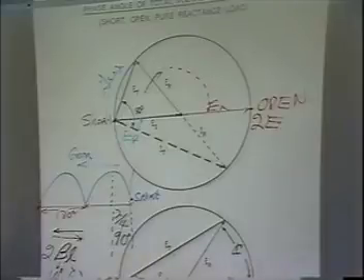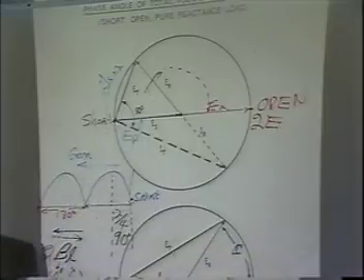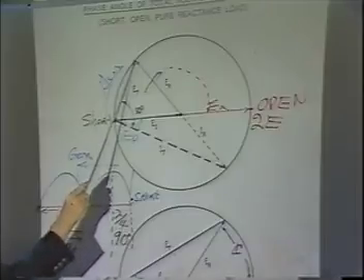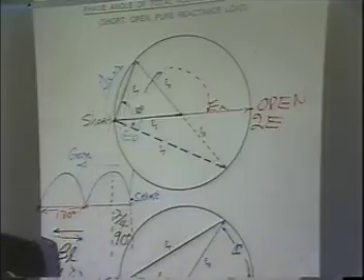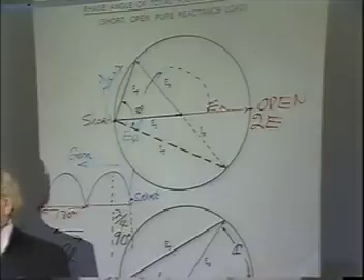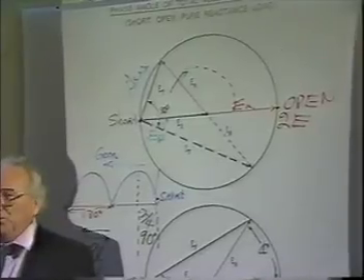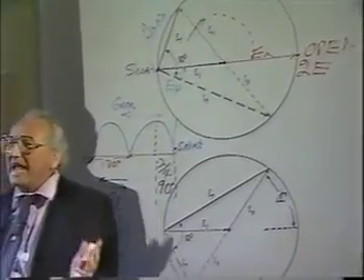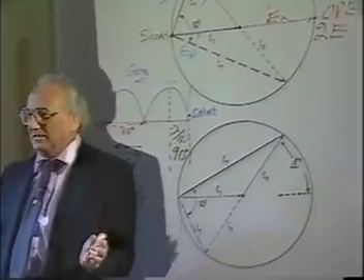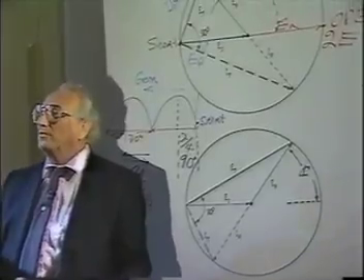Now let's think of this from a logical standpoint. I put this on the exam and several of you kind of missed it. I said if you terminate something in a pure inductance, how much of your voltage is reflected? Well, there's only one thing that dissipates power and knocks down the voltage. That would be a resistor, wouldn't it? This is not a resistor. It's a pure reactive circuit. It's a pure inductance. Doesn't inductance dissipate power? No. So you still have total reflection with voltage, wouldn't you?